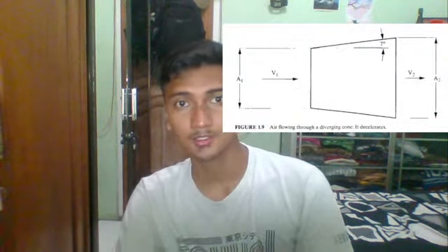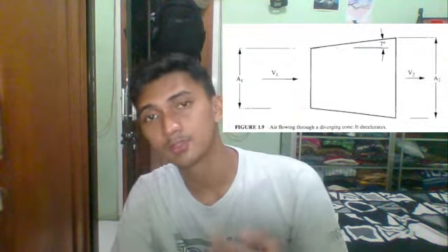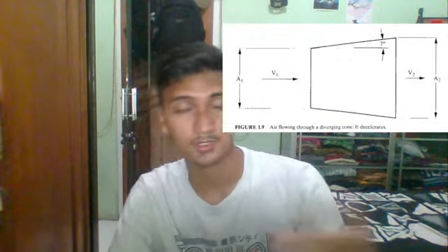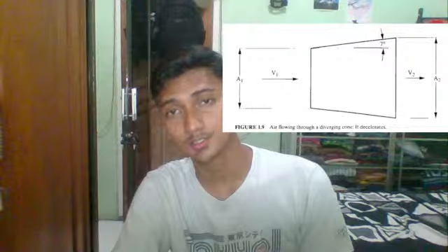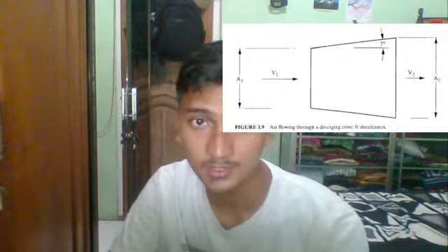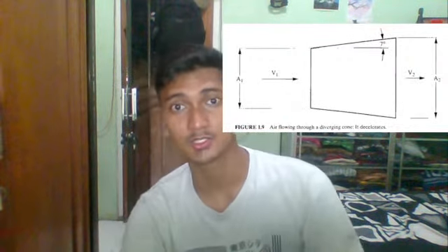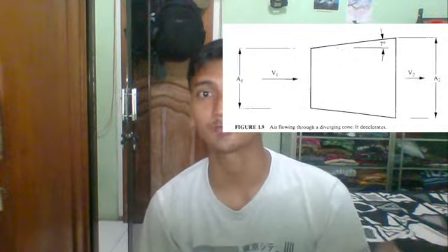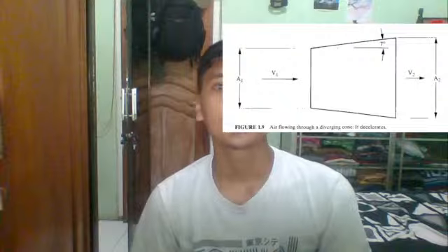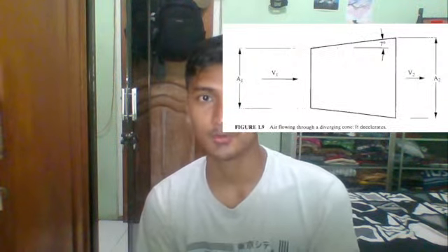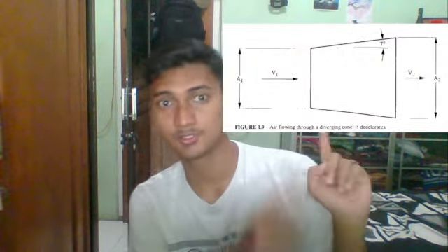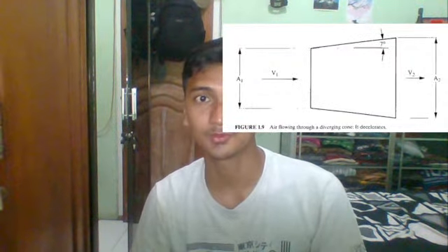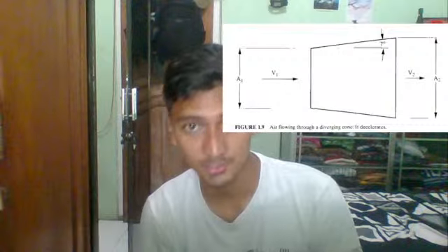As discussed earlier, a converging cone, as shown in the figure of the converging system, will produce an increased velocity past the cone, resulting in increased kinetic energy, which is obtained at the expense of decreased static pressure, right? By the same token, a diverging cone, as shown in this figure, will produce a decreased air velocity past the cone, resulting in a decreased kinetic energy.